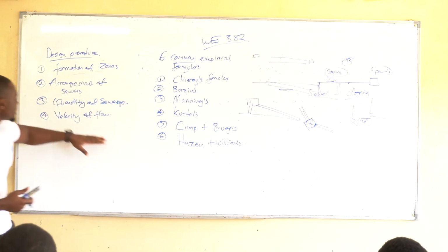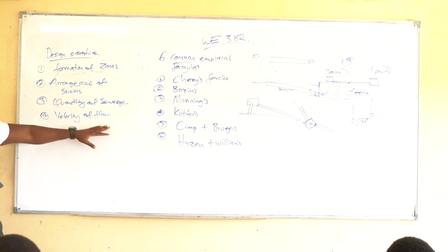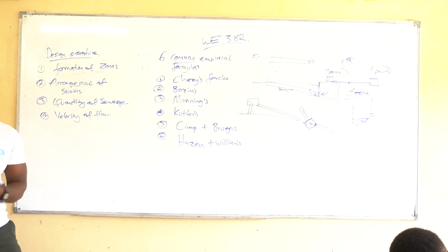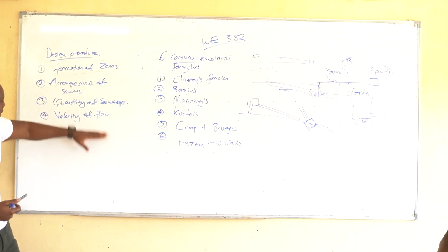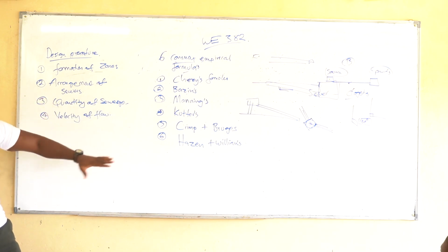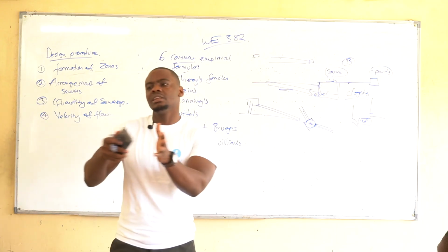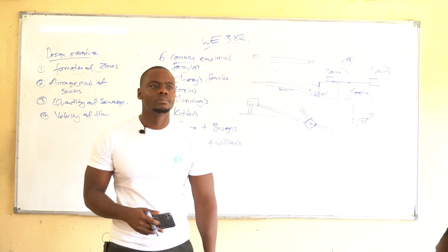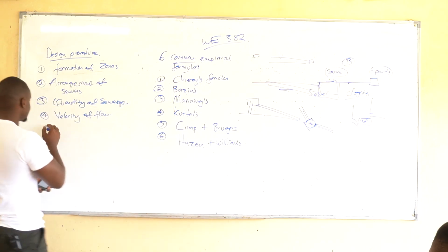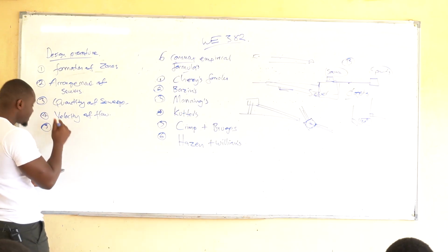The speed at which the fecal waste is moving is really important to us. It can't move too fast because there will be friction, and then you constantly begin to change your pipes, which is bad. But again, it can't move too slow because you're likely to block everything. So we had a formula last time where, given the conditions, you can decide the velocity that works. Last but not the least, when you're designing, you need to consider the section of sewers.